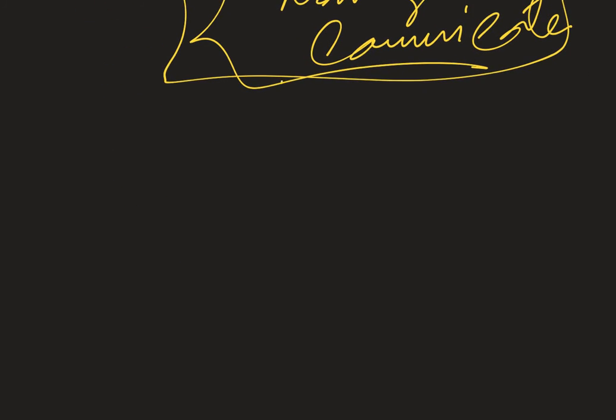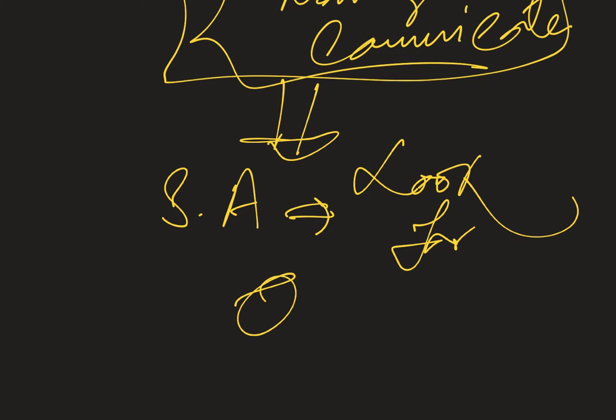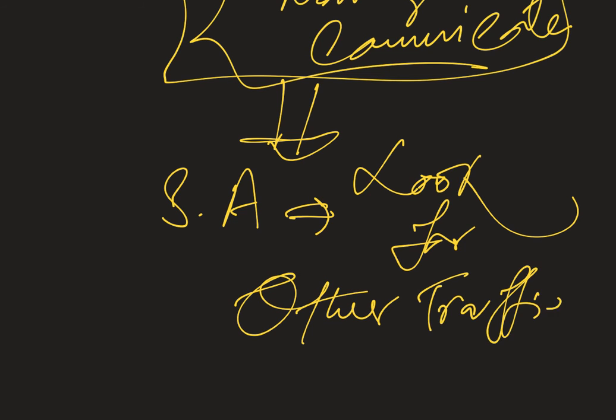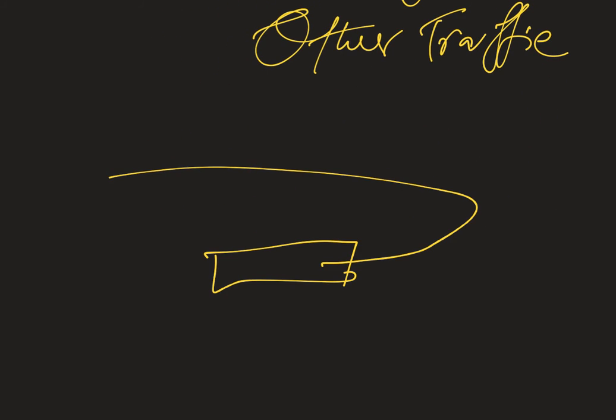Next important is situational awareness, and look for other traffic. For example, if you are in the pattern and making your approach, look if there is another aircraft which is taking off, or maybe at the holding point. You are not yet given your landing clearance.